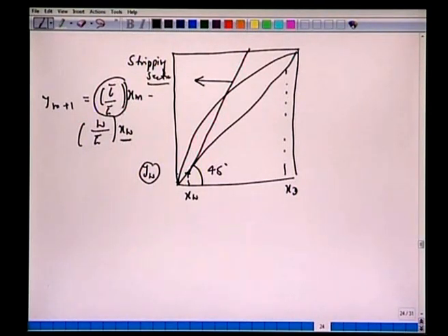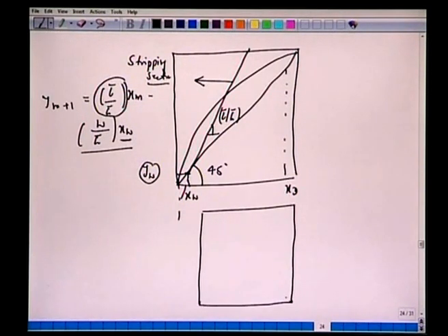Again, make a note here that suppose somebody starts with the slope and the intercept, which should be negative here. One will obtain the same line, but there's no point. It's rarely done like this, because we realize immediately that xW and yW lie on this 45-degree line as well. So if you put it here, we'll get the same results. It's better to start from xW, yW on the 45-degree line and take the slope of L bar over G bar to obtain this line here. Alright, now we can start construction of the plates in the stripping section, the way we have done it for the top section.